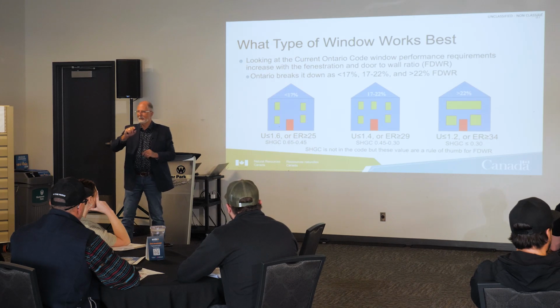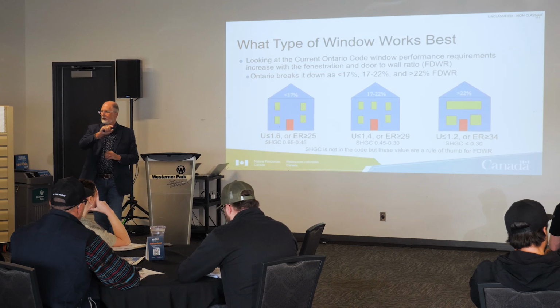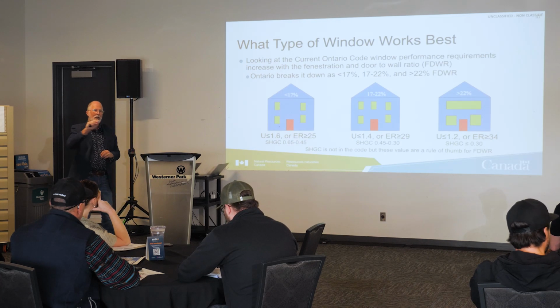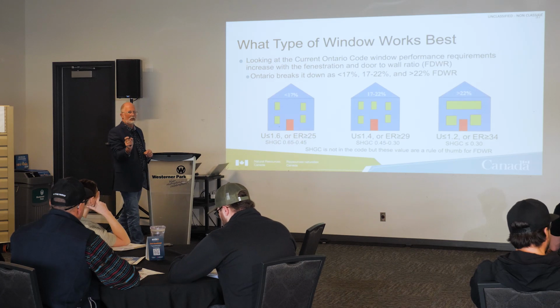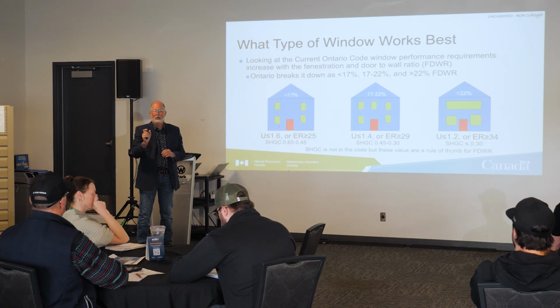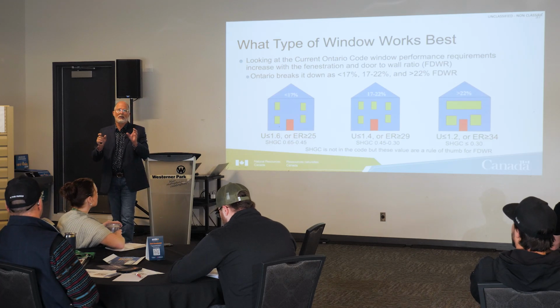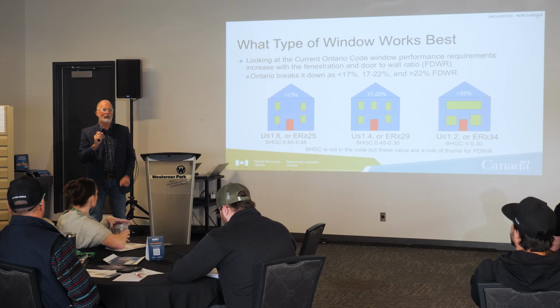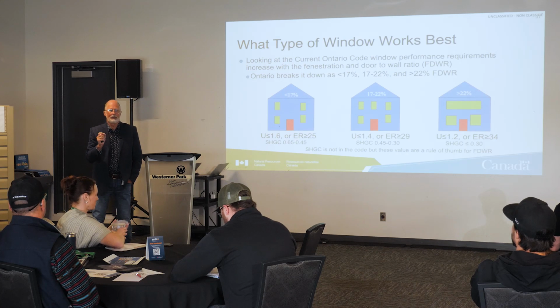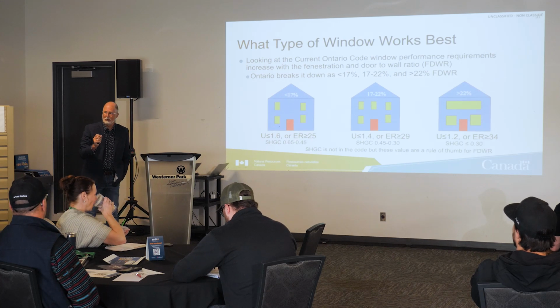And there's a little line about 3/4 of the way down on your 2000 report that'll say peak cooling load. And you'll either have it in watts per meter squared or you'll have it in BTUs. And you compare that to the reference house. And what it's telling you is when you're overheating that building. So it's a very valuable number. And your energy advisor can go through that with you.